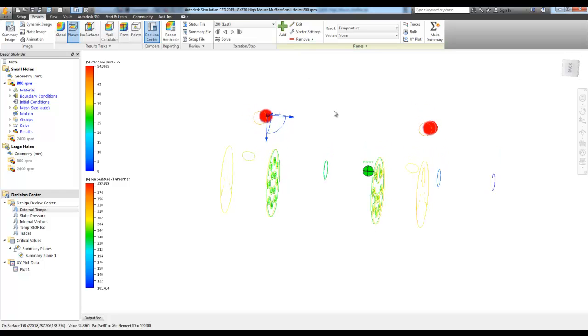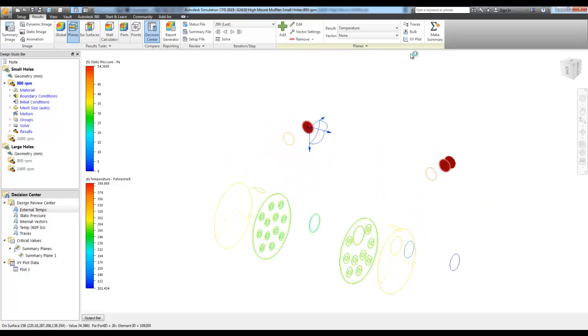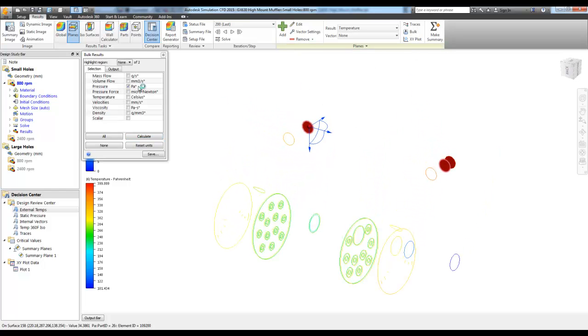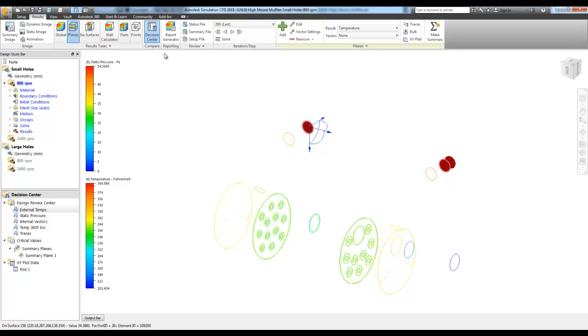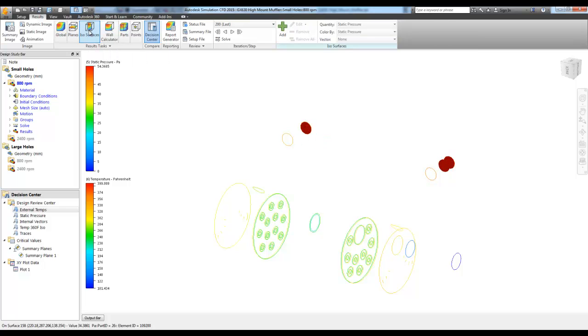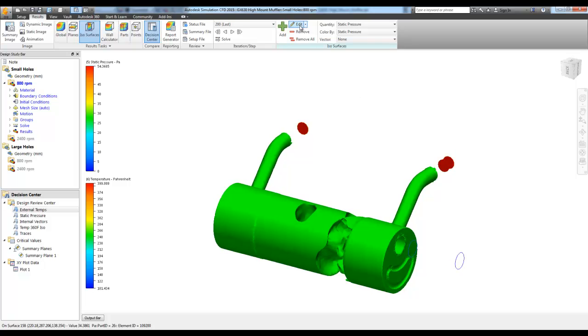The other thing that we can do with this is also to look at the difference between the two cylinders by use of the same cut plane. So what we'll do is we'll insert a cut plane, cut through both of our inlets, and now look at what the bulk pressure is between the two. And we can see with this first pass scenario, we're about plus or minus 4%, which might be outside our windows of what specifically we need for this design.